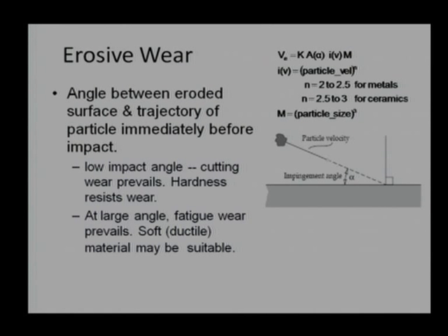Whether it is a low, medium or large angle, the characteristics will be different. If the particle is coming at a low angle, the angle of inclination is lower, the value of alpha is lower, like 5 degrees, 10 degrees, 15 degrees, then particle shape will also matter. How it collides with the surface matters, as we know very well the kinetic energy will not be transmitted as much as it can be transmitted at alpha equal to 90 degrees.